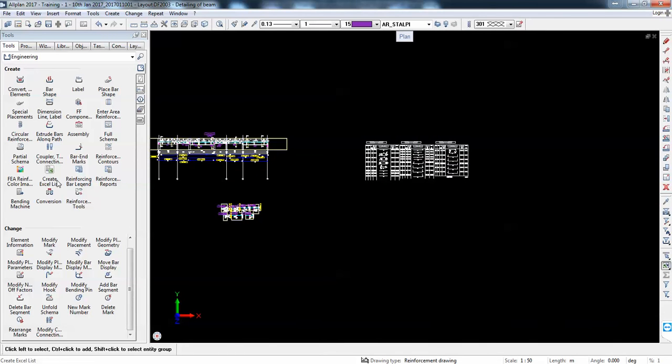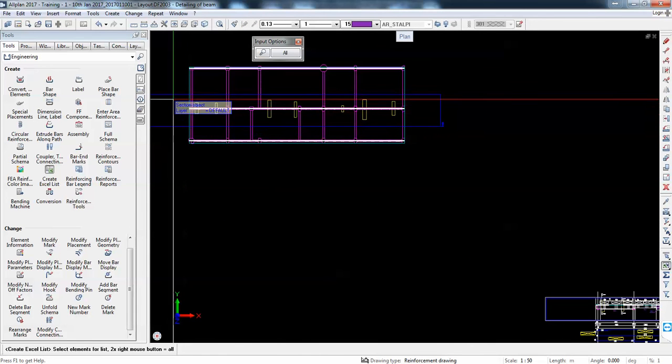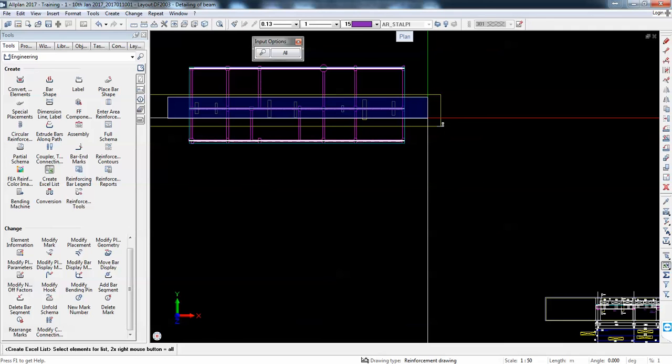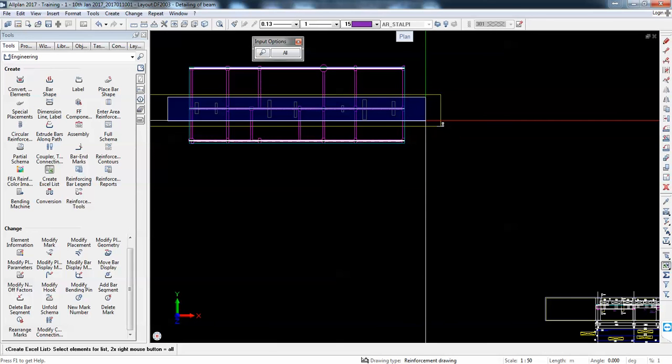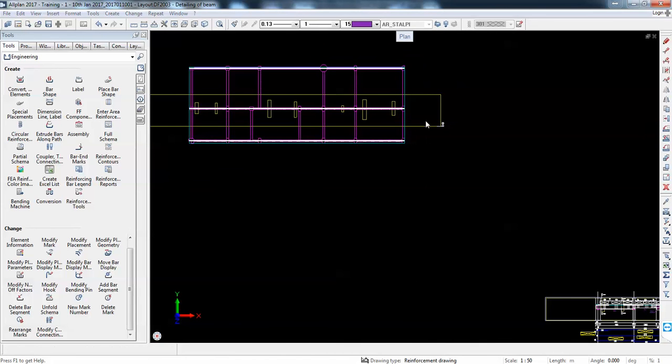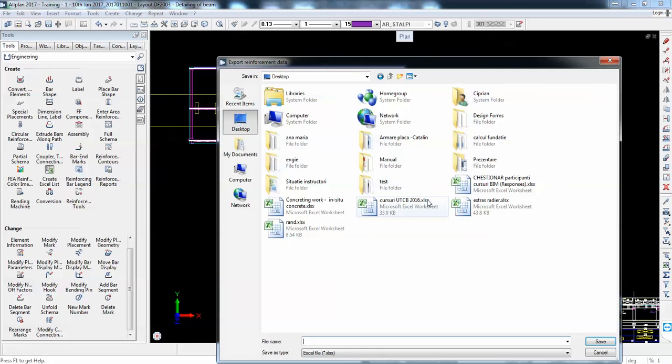And also we can have the option with Excel, but what is important to know is that the Excel allows us to select rebars, but it will not count only the selected, it will count the selected marks. So if I select 3 bars that are here and in the other beams as well, all are counted. So this count, although it allows selection, doesn't mean you'll get the reinforcement only for the selection. You'll get the reinforcement only for the selected marks that are placed in the entire drawing, not only the selection.